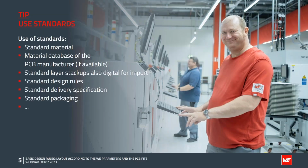Another tip for using standards. Standards are the basis for quality and efficiency in terms of error prevention, increased productivity, reliability, and last but not least, safety. So we also have standard layer stackups, as already mentioned, also digital for import in your EDA tool. We have the standard design rules, we have standard delivery specifications, standard packaging, and so on.